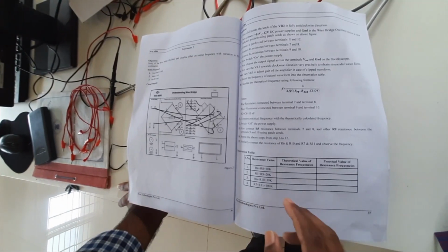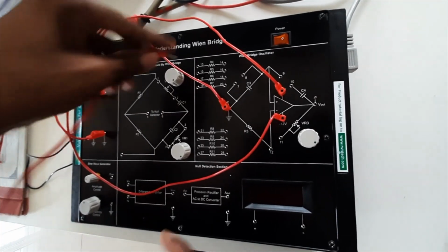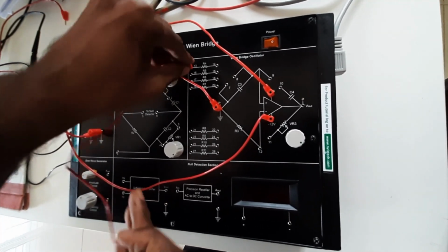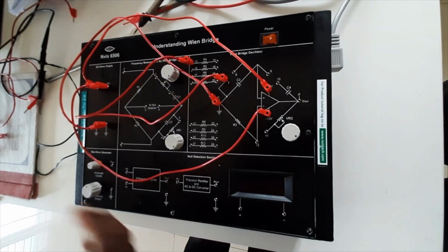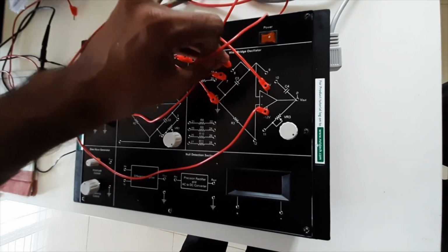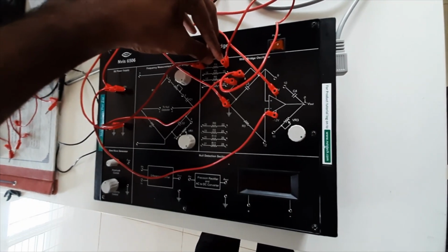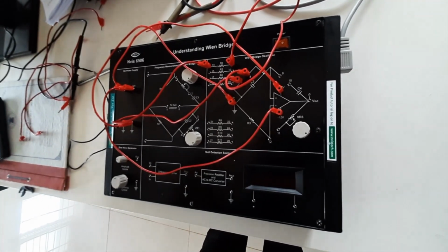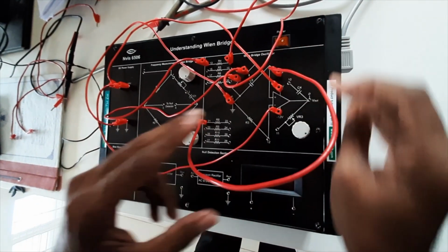Now, first of all, in this table we are going to set the R4 and R8 values as 10 kilo ohms. Let us connect that. So here I am selecting this R4, which is connected in one of the bridge arms, and this 14 is connected to here. So this R4 value, internally how much is it? 10 kilo ohms. And next we are going to connect this R8 between 9 and 10.